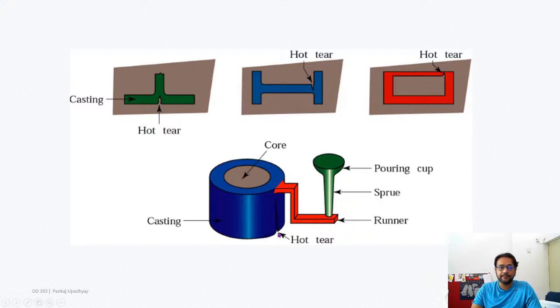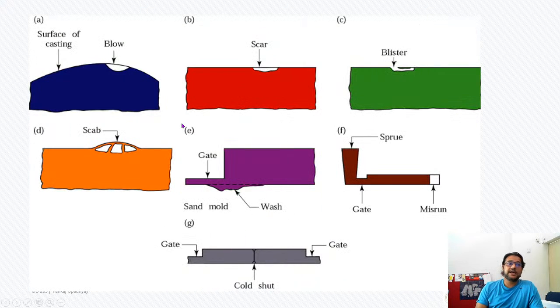So something like that. Okay, and so these are other surface level imperfections, the top three that can be commonly seen. So the first one is a blowhole. The blowhole is directly because either water vapor or air got entrapped in the surface. As you can see, this is a high surface, like a dome type of surface. So chances are the air will get trapped in here, and there's no vent for the air to move out, right? Because of that, the air gets trapped in and the material cannot flow into that, and because of that you will get these blowholes.